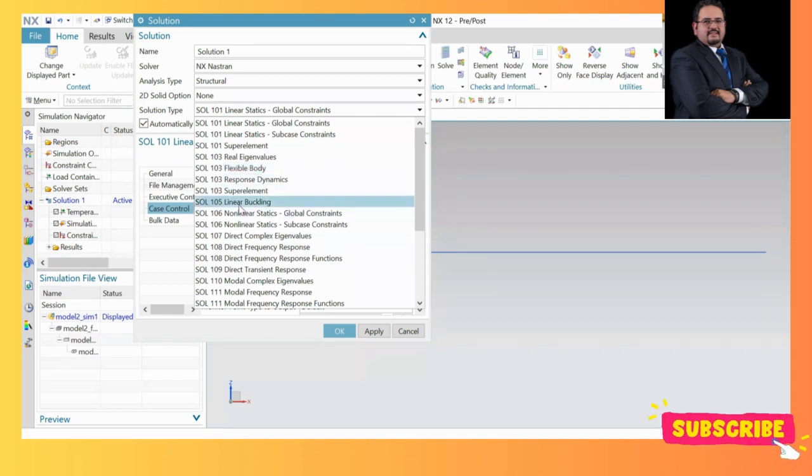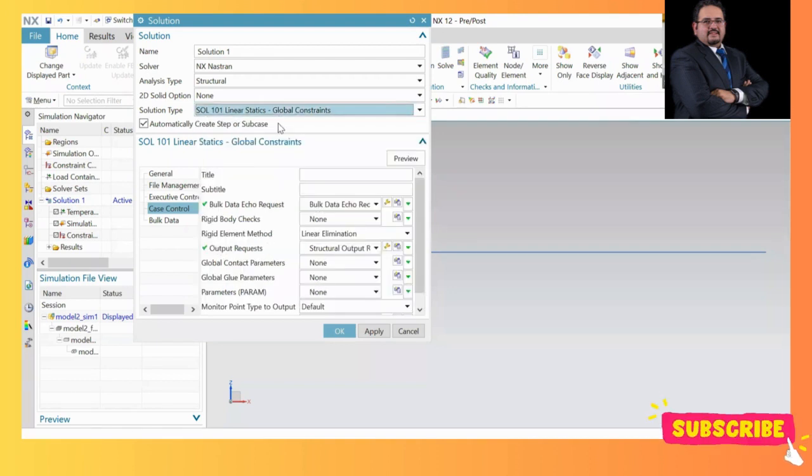This is again for buckling. So based on the type of problem you are doing, you can pick the solution type relevant to that one, right? If you want to perform a generic one, you go with the regular linear statics option in this case, which is this. The other thing I am interested in is what type of outputs I'm getting.